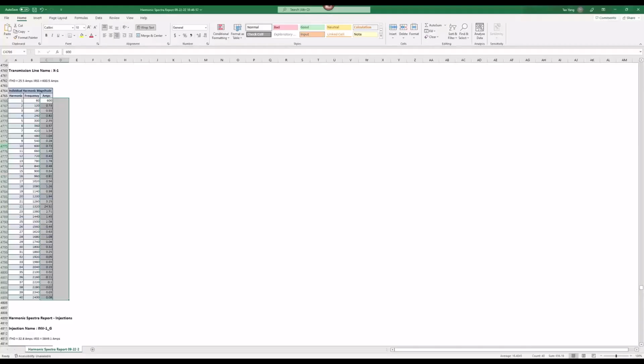Usually in EasyPower, we only model current injection. If you want to model a harmonic voltage source, I think we have other webinars to discuss how to do that. Actually, it's not up to you. It's up to the manufacturer. If the inverter is provided to you as a current injection model or a voltage injection model, then you can pick and choose, right?